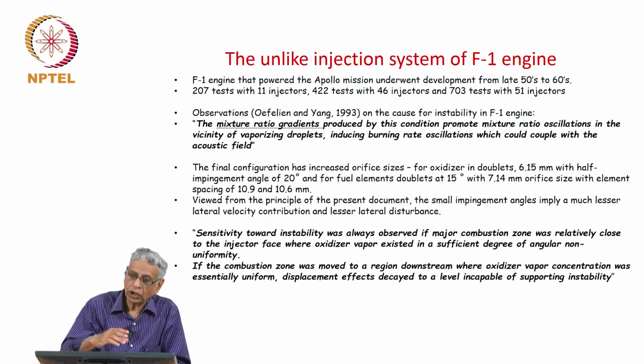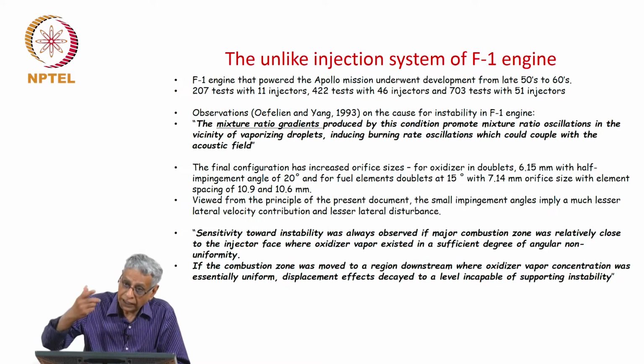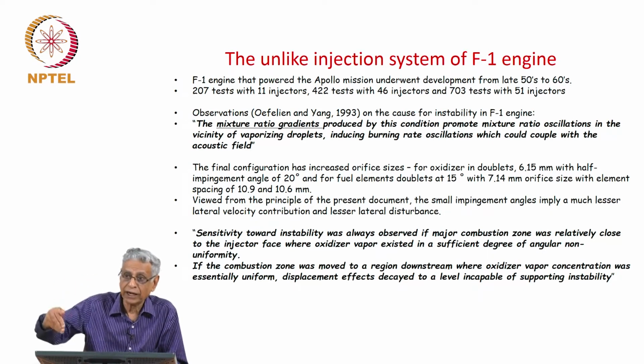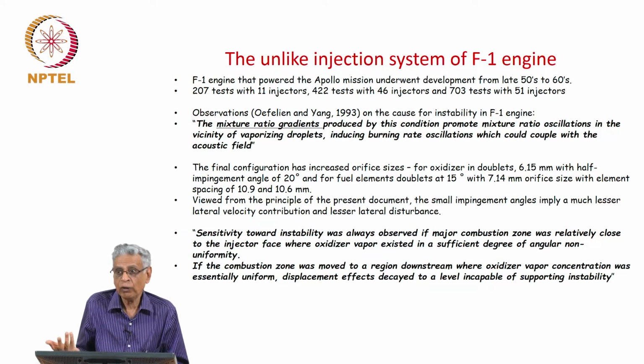If the acoustic oscillations interact with the heat release profile, and that occurs very close to the point where the droplets are present, then the mean free flow field is also affected by the acoustic oscillation.